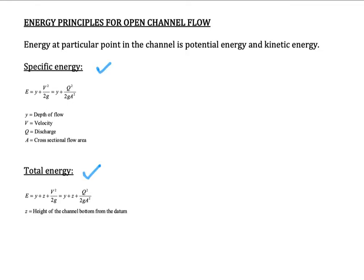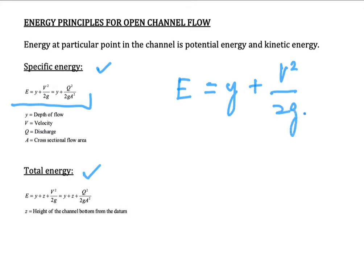For specific energy, it can be written like this. We have E, which is the energy, and it is equal to y plus V squared over 2g. If you see the equation here, you could find that V squared over 2g is similar to the Bernoulli equation, and y here is the depth of flow, meaning the height of the water flow.